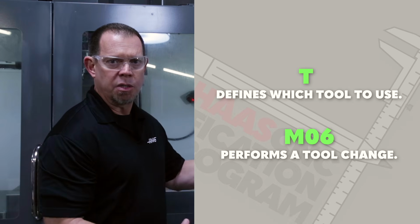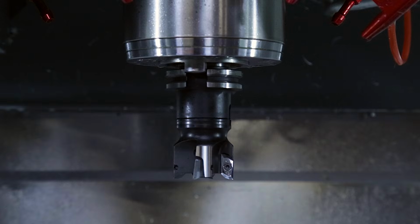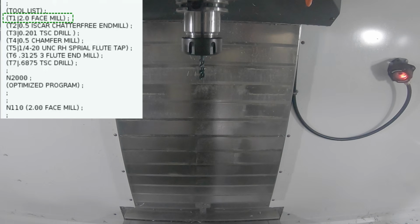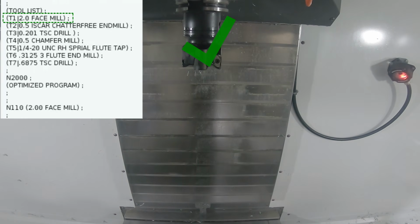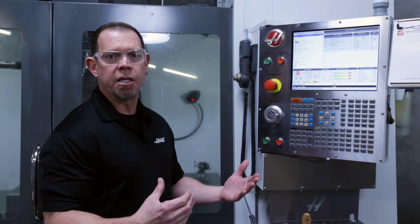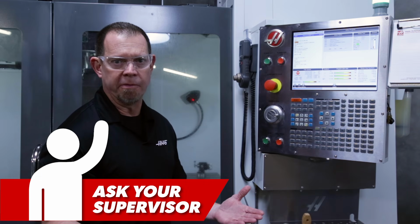This T code defines which tool to use, and the M06 is the command to perform a tool change. If that tool is already in the spindle, no tool change will take place. Now in this case, tool 1 is not in the spindle, so you will see a tool change. Now is a great time to compare the tool described in the comments to the actual tool in the spindle. Here in my program comments, I see that tool number 1 is a 2-inch face mill, so I'm good. But if I start the program running and I see a drill loaded in the spindle, now I know something's not right. It's time to call my supervisor.